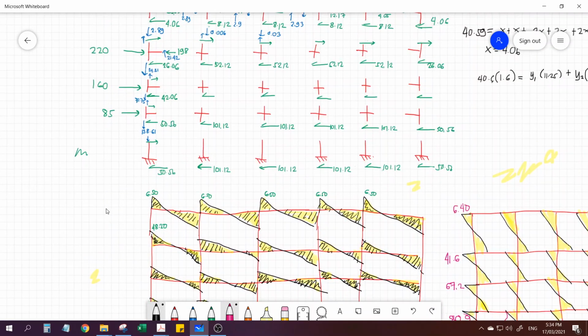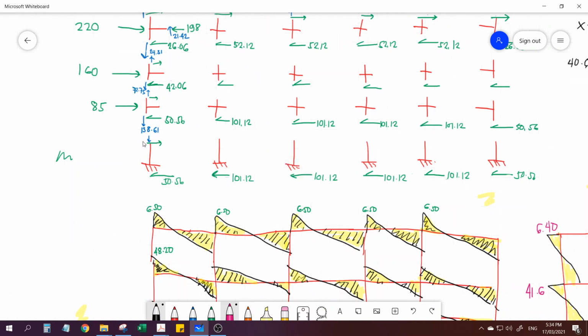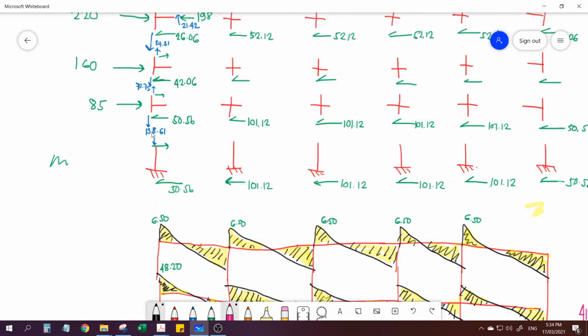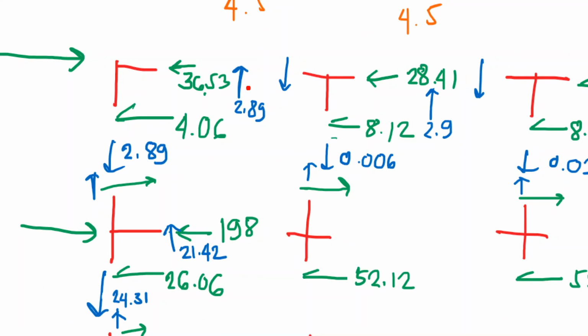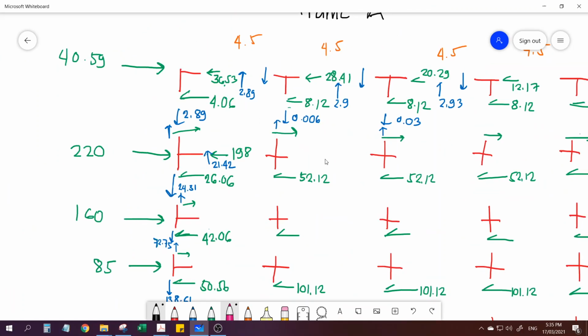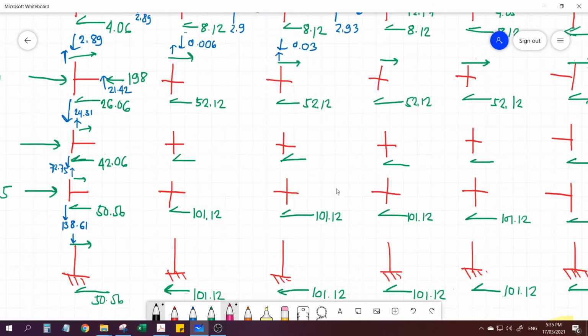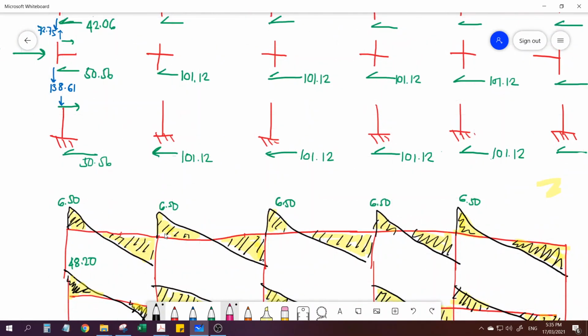Then for the moment, so moment later mo na makukuha yan kasi after mong matapos yung calculation per joint. So how do I get the moment sa say halimbawa dito sa girder? After getting yung na to, yan, 2.89 multiply mo sa distance which is 2.25, half ng 4.5. So 2.89 times 2.25, that is 6.5. 6.5. Okay. So ito yung moment sa ating girder.